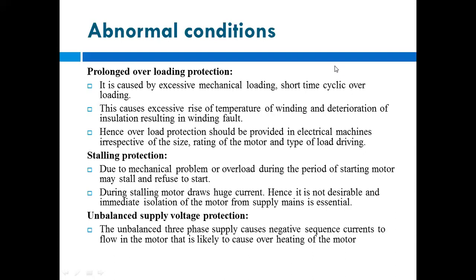All of you know that when load increases, the current increases, right? If the current increases, the temperature increases, and if the temperature increases, it will heat the winding and deteriorate the insulation. म्हणजे insulation तुमचं खराब होणार आहे. So resulting in the winding fault.